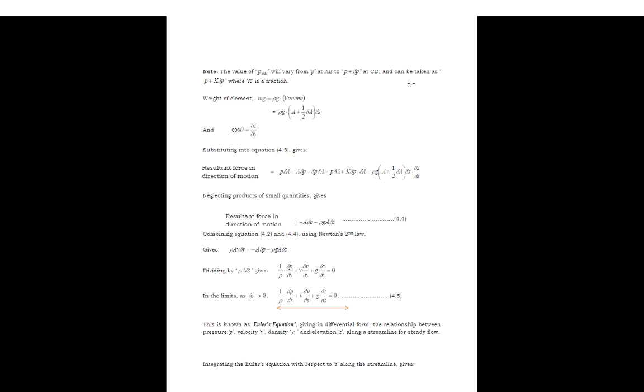This conservation of momentum for a frictionless fluid, using the Euler equation, when you derive it, brings us to an equation that we call the Bernoulli equation. This equation is based on two properties: a frictionless fluid, and that the same properties are constant in a system from one point to another as long as there is flow.